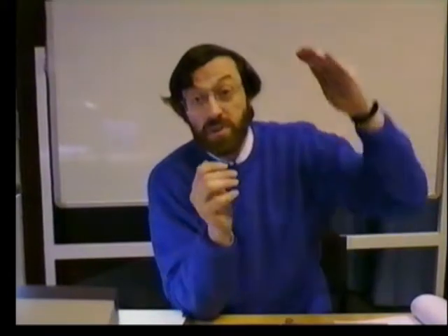job. It's pulled the steady state error up through the measured variable, up through the set point, we've oscillated around, and we have finally settled down. Let's see if we can get that a little bit more exciting. Let's have a proportional term of 40, an integral term of about 5, short delay.